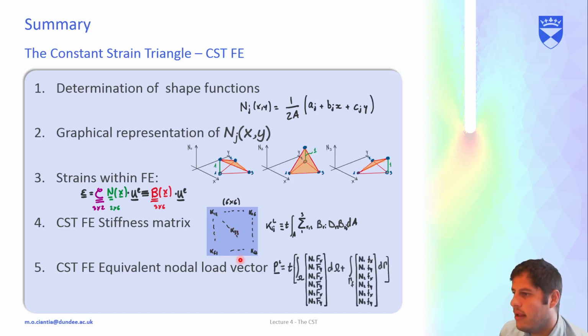Finally, to calculate the equivalent nodal load vector when we use the CST, we've seen the generic theoretical description, but also this way to consider an equivalent simply supported beam to calculate the pressure loads, or distributing the body forces evenly to each of the 3 nodes.